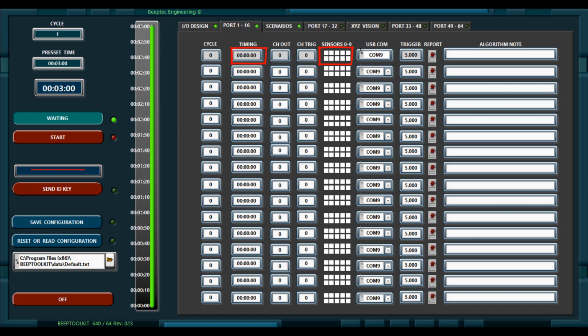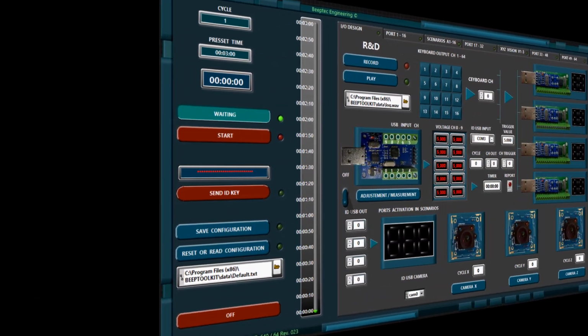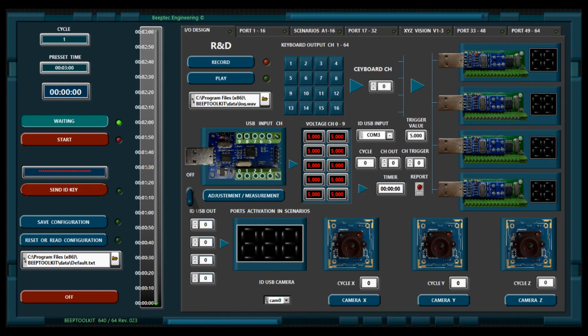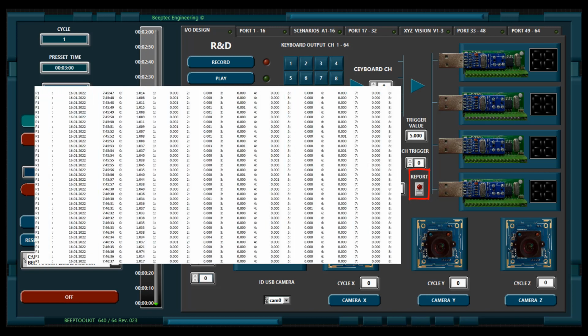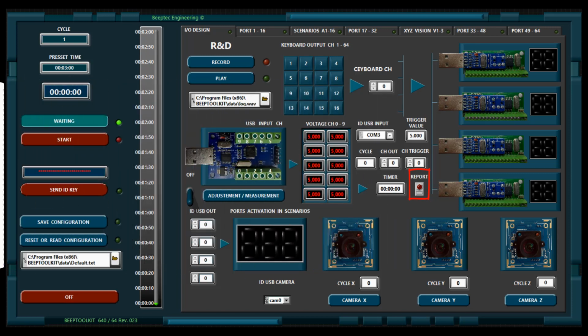If you do not specify an output channel, but only include input channels, this will be a set of measurements over a certain period of time. During development, it is often necessary to make preliminary measurements of the sensor data, for example, to characterize the sensor, calibrate it, or derive a threshold value. For statistics and analysis, you can create and save data collection reports in the desired time interval. These are very convenient and popular features that should always be at hand.